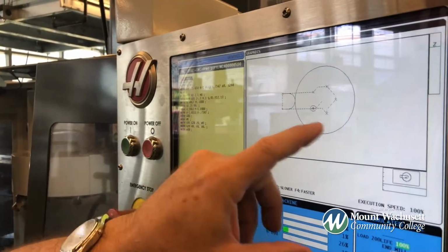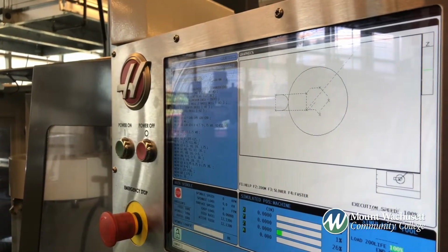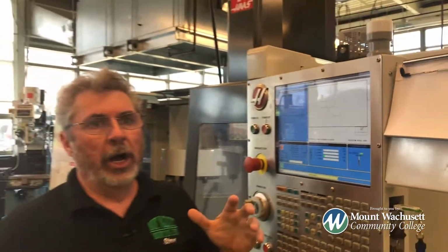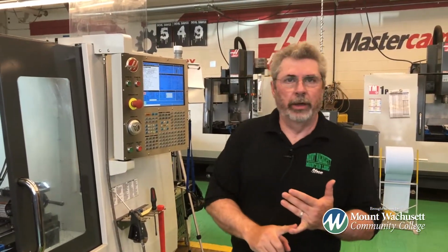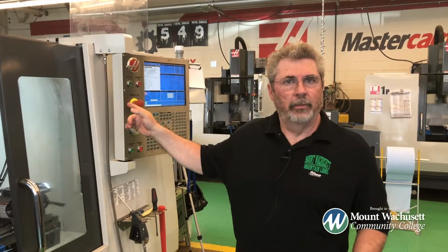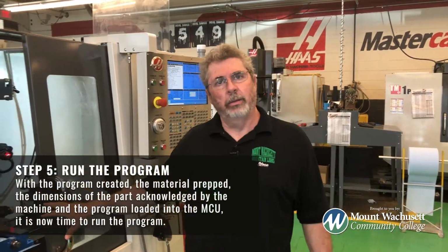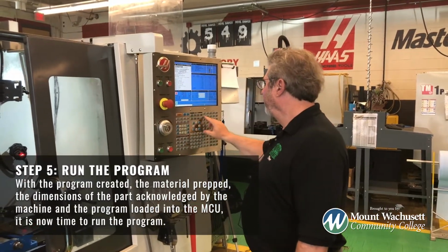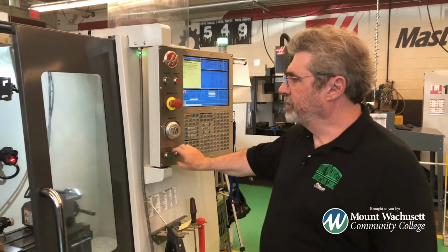There it is. It cuts a circle and it's going to go around and drill those holes. This is the actual simulation of it. It's really not a great 3D visual, but it gives you a great idea if you have the right program called up and if the cutters are going to the right locations. You've seen us download the program. You've seen us simulate it. Now we're going to actually run the part. That's our next step. I got it up in the window. Hit the cycle start button.